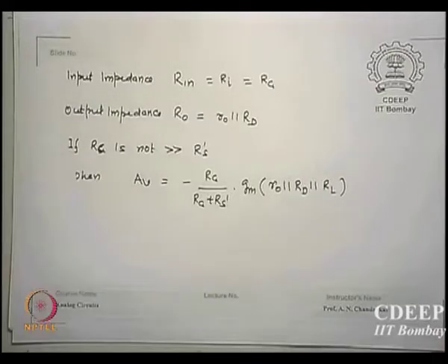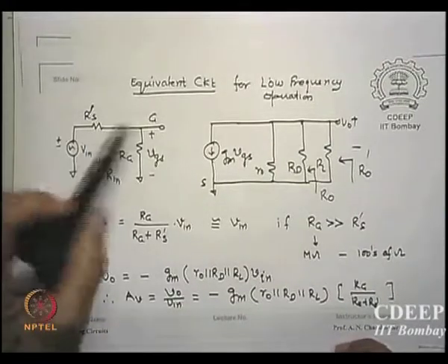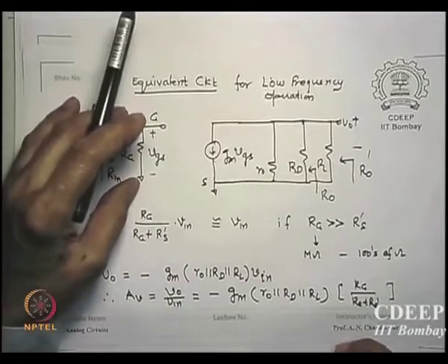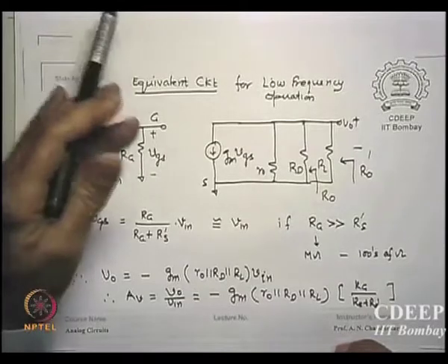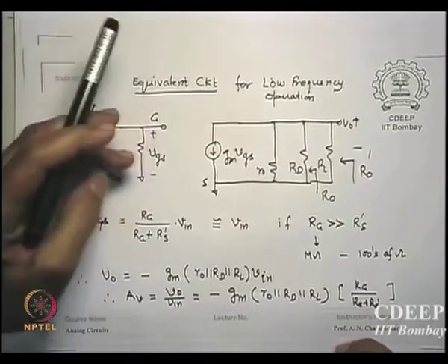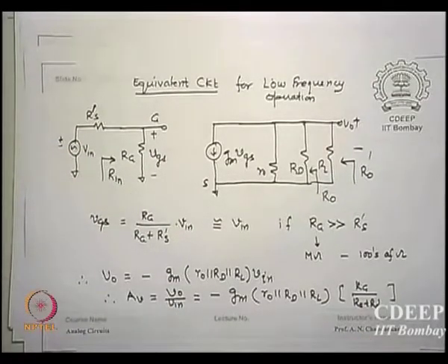then one can see from the circuit, as seen from here, this is the only resistance it is seeing. So whatever current is entering, V by I is only Rg. Whatever is the voltage here divided by the current is the same as Rg. So input resistance is Rg, very high. How much will it be? In mega ohms, because Rg1 and Rg2 also are in mega ohms. So because of them we will always have Rg very high. Is that correct? Rg very high.